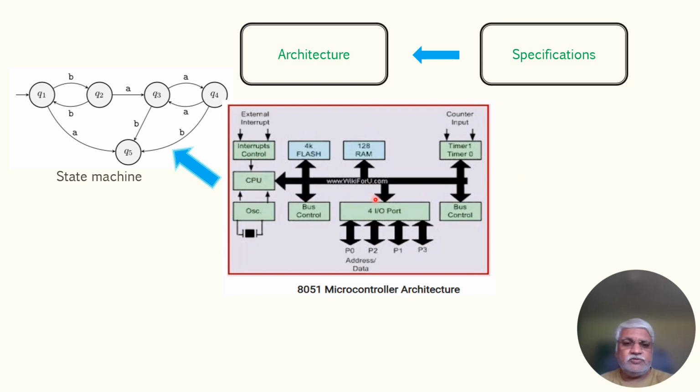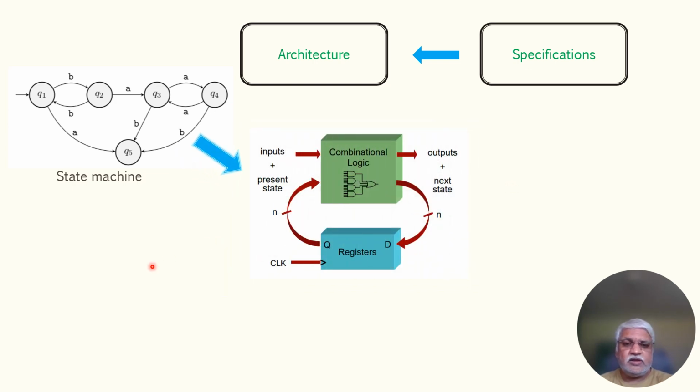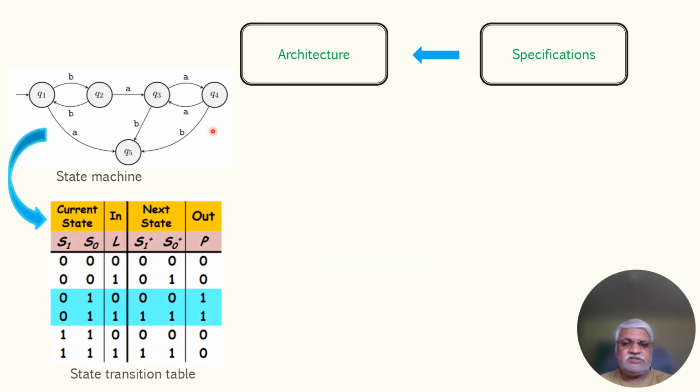And if you see here, in undergraduation we have studied the state machine in terms of Mealy or Moore machine. Here there will be some inputs and combinatorial circuits, and it will have an output. Based on the next state and other things, the data will be stored in the register, and then it will again be sent as a present state to this. Then all these things will be evaluated, and the new outputs will be generated. This will be based on whether it is a synchronous machine or asynchronous machine. It will be triggered appropriately.